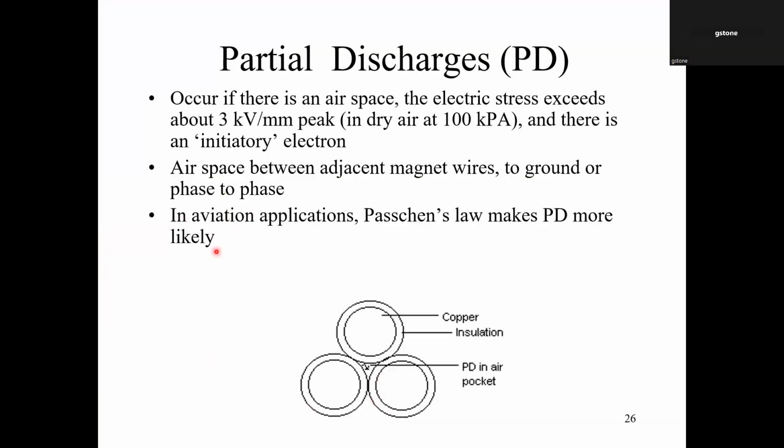Also be aware of that if you're at lower pressures, because you're at higher altitudes in aircraft. This is why I'm a little concerned when I get into certain modern jets when I'm flying between continents. You're at much lower pressure, and therefore there's an even lower breakdown field strength needed to break down that air.